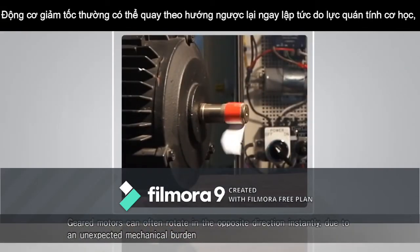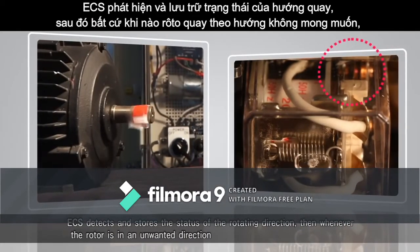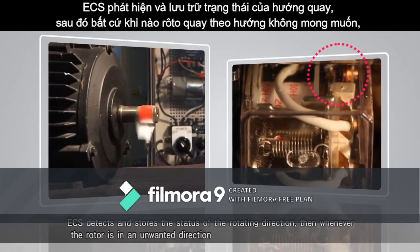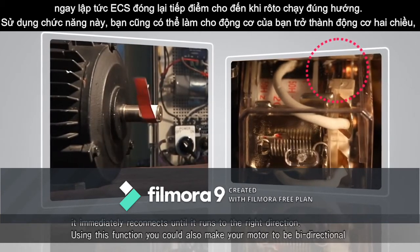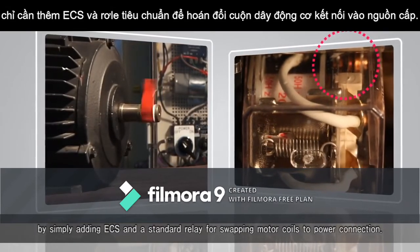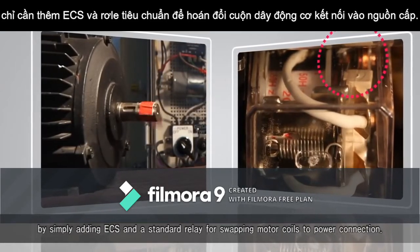Geared motors can often rotate in the opposite direction instantly due to an unexpected mechanical burden. ECS detects and stores the status of the rotating direction. Then, whenever the rotor is in an unwanted direction, it immediately reconnects until it runs to the right direction. Using this function, you could also make your motor be bidirectional by simply adding ECS and a standard relay for swapping motor coils to power connection.